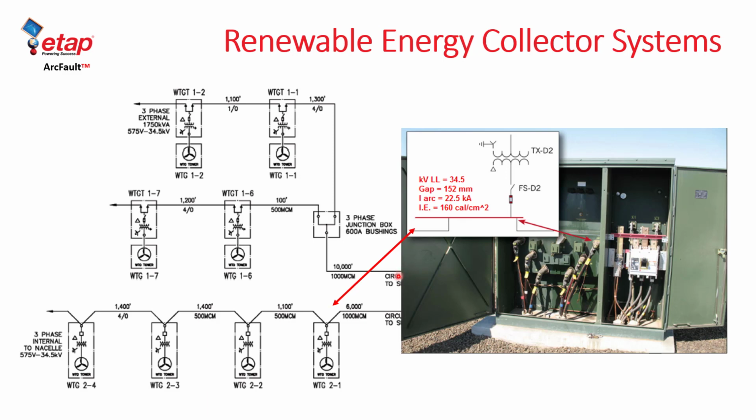What's important to note here is that typically these transformers are placed at different locations, the most common of which happens to be open-air enclosed configurations placed on pad mount areas or pad mounts. For such equipment placed in open air, there is still an arc fault situation where you have typically three phases incoming in the collector system, and where you also have exposure to the low voltage side, operating typically between 600 to 900 volts AC.